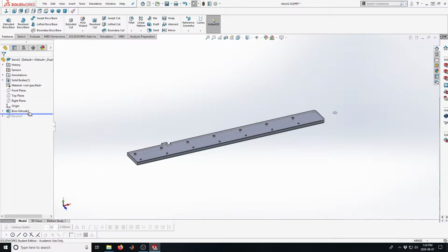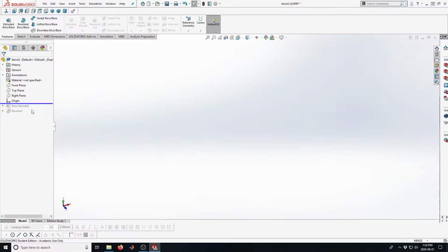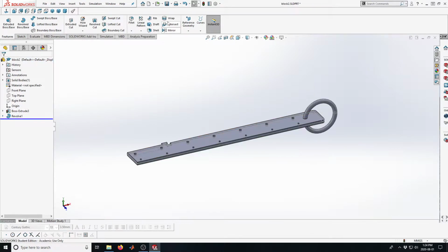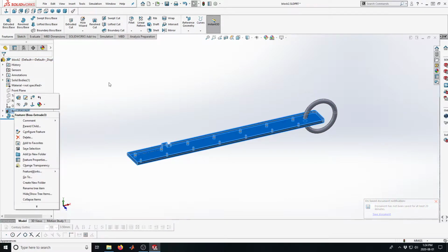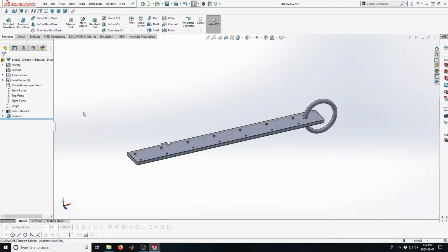And you can roll back the feature to eliminate it, even the original feature, as far as you like in the feature tree. When you do roll it back, of course, it will need to be rebuilt before it's happy again. You see here I rolled this back and now it's got a stop and go light showing for that original thing. You can right click on it and see what's going on with it. You can click the rebuild button at the top. Often that doesn't actually do anything, I find.